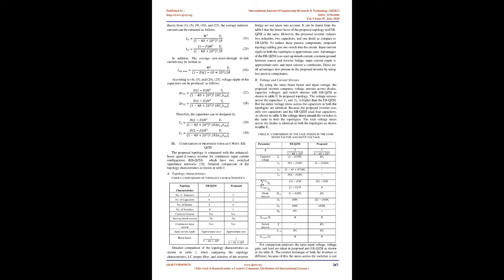As shown in Figure 4, in one switching cycle, 2 shoot-through states occur. By using the SBC, current stress around the switches is halved as compared with the control method in reference 5. In a shoot-through state, a 2-phase leg is switched on simultaneously under the SBC, although only one-phase leg is switched on in the control technique of reference 5. By controlling the modulation index, we can control the duty ratio in SBC as follows. Fig 4 shows the PWM control technique for the proposed inverter.